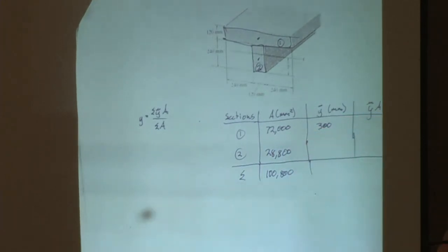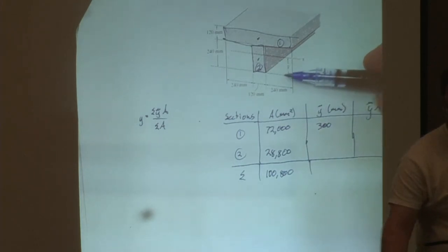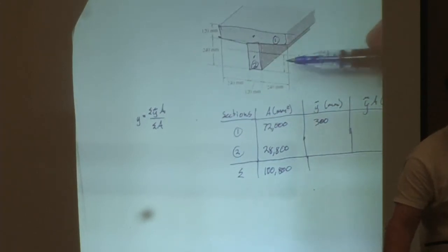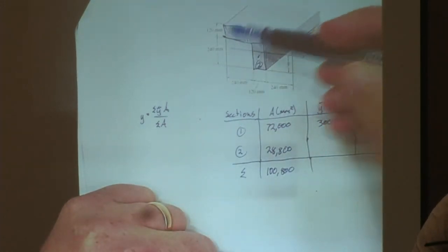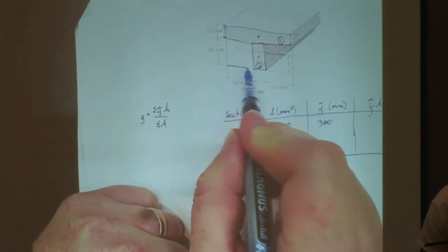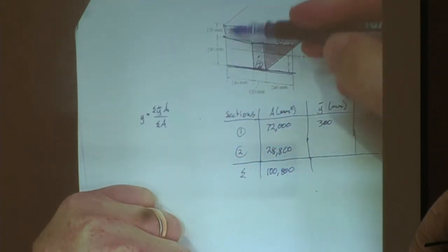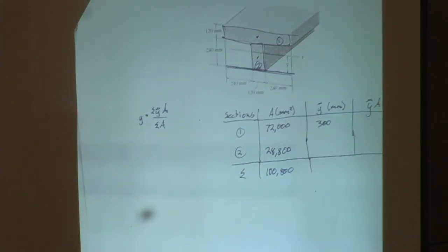Does everybody understand how we got that? No? All right. Would you like to explain it? When you're doing the y bar and you have it above the second one, you have to add the distance from it below and then do half of the y, which is 120. You do 240 plus the 60 to get your actual location, if that makes sense. You're just trying to find the y coordinate of the centroid to the figure you're trying to do. So from here, he did 240 plus half of that, and that was the centroid of that, because we're looking for the total in y, so we need both.